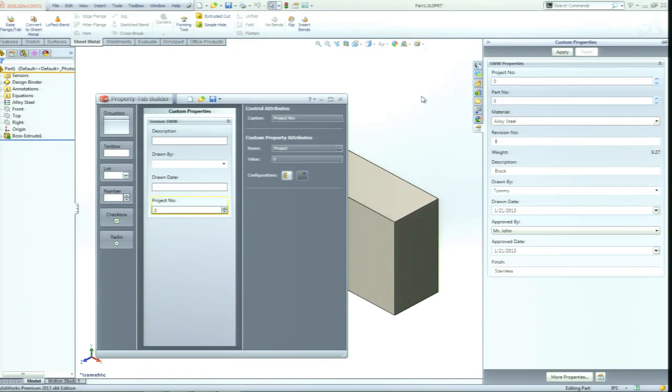Okay? Another neat thing with SolidWorks, and this just came about recently, and this doesn't have anything to do with properties or sheet formats and stuff, but as far as sheets are concerned, if you do a lot with configurations, you now have the ability to copy and paste sheets, not just within that file, but outside of that file.